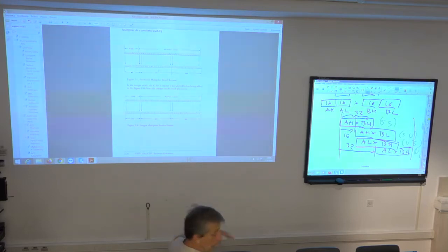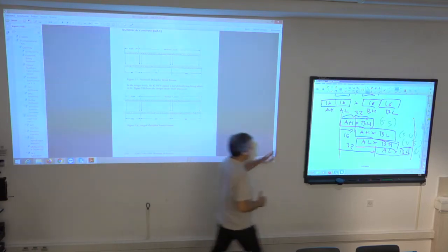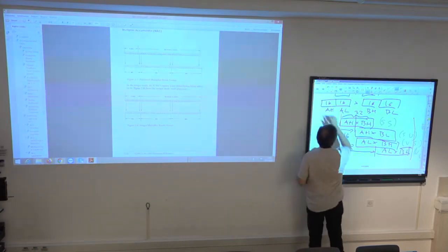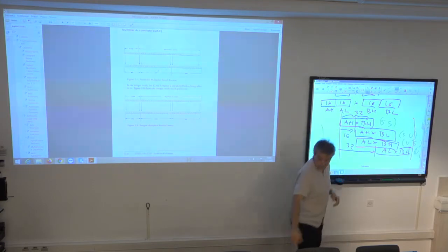It describes here, because this multiplier can also operate in integer mode, not fractional mode. And that means it interprets the data as the decimal point being at the rightmost place. So, for example, instead of having the decimal point after the first bit, as is shown here, now I have to put it here.